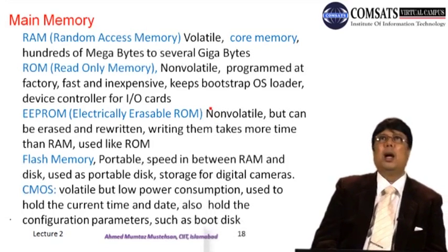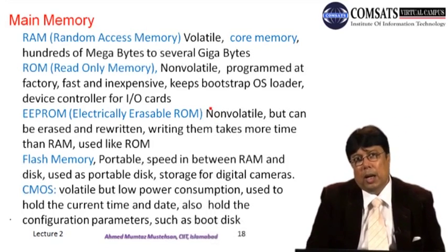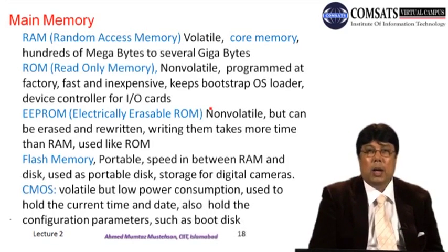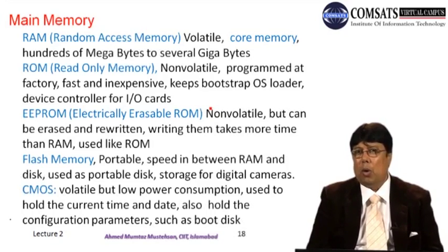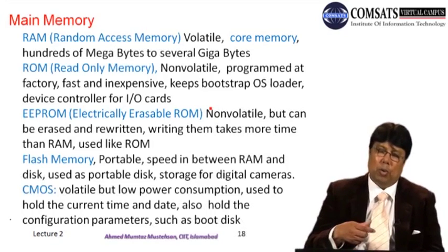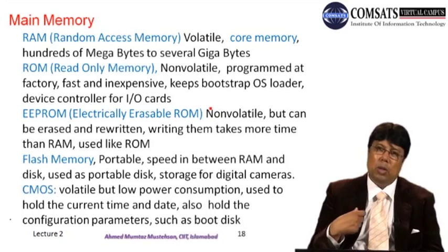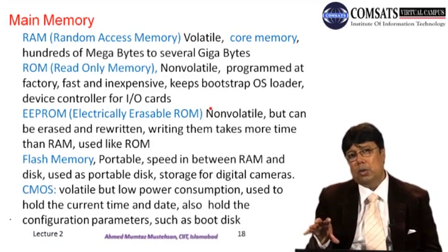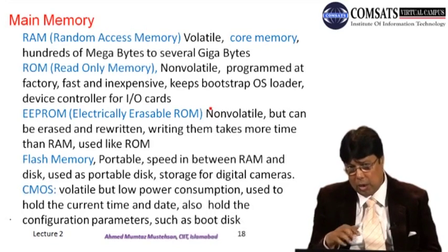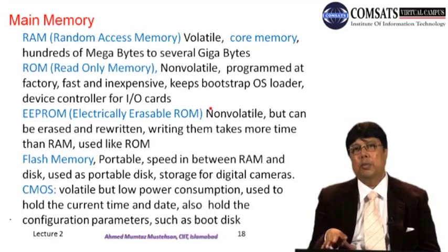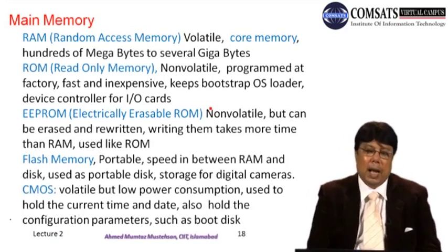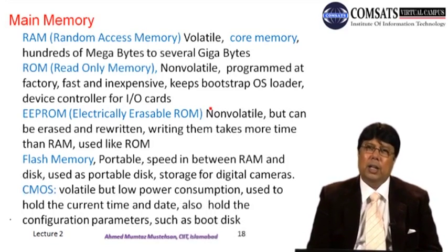इससे पहले एक और भी आई थी जिसको हम कहते थे EPROM, erasable programmable read only memory। लेकिन वो जो इरेज होती थी वो अल्ट्रा वायलेट बॉक्स में रख के फिजिकली वी वर सपोज टू टेक द चिप आउट, हम उसको चिप को निकालते थे, एक बॉक्स में रखते थे, उसमें अल्ट्रा वायलेट लाइट होती थी, एक विंडो होती थी उसके ऊपर चिप के ऊपर, उससे लाइट उसके अंदर जाती थी और डेटा को इरेज करते थे। That has been obsolete with the invention of EEPROM। EEPROM है electrically erasable।